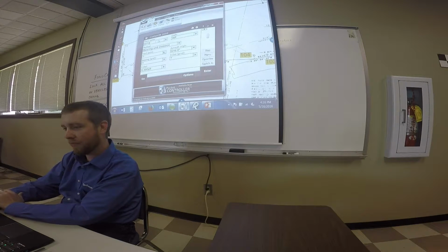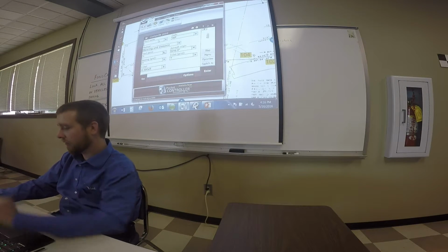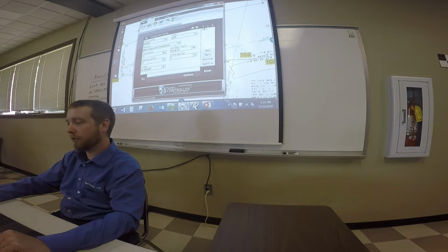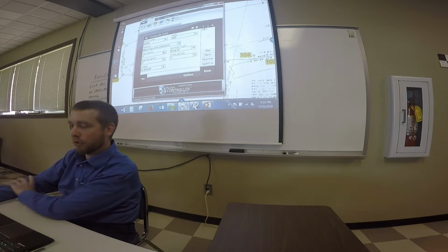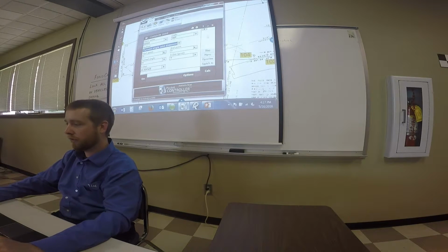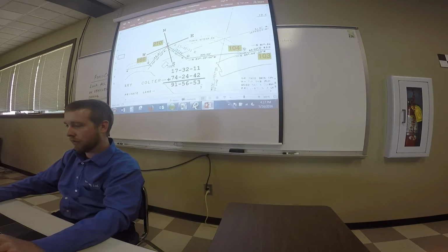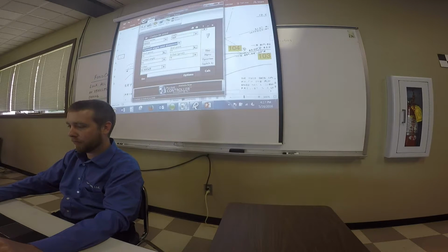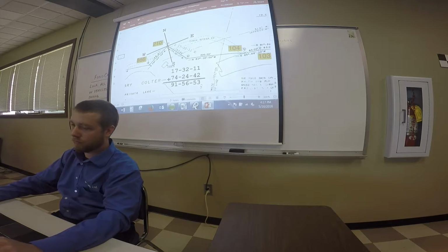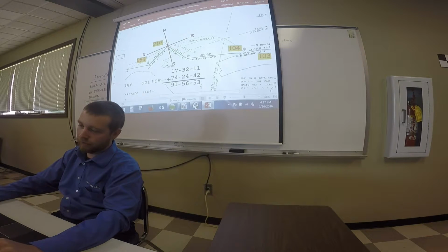Okay. We're going to go 0.9000. We're going to make a new point using that turned angle. We're going to go to the drop-down menu, go turned angle and distance. Now the point we're going to start at is going to be this point up here, number 210. Our ending point will be our backside, if you will, down here, number 886.